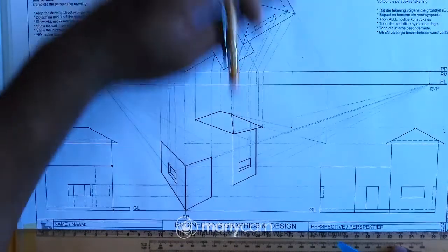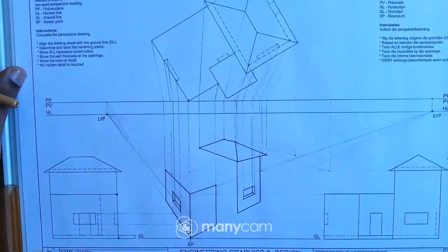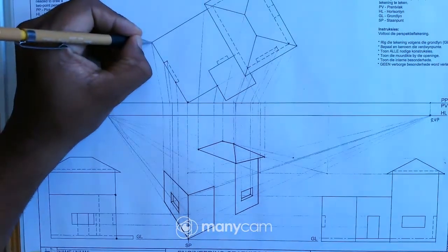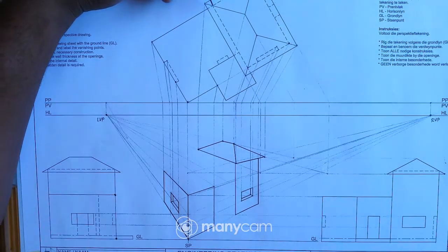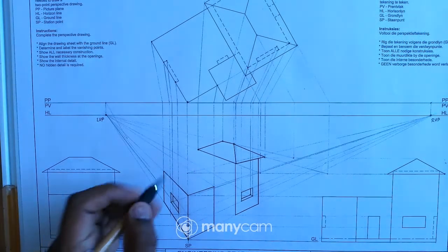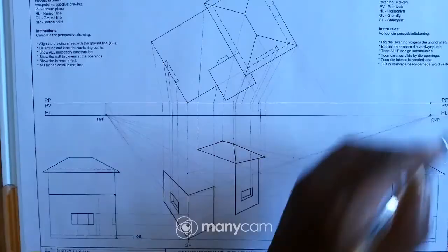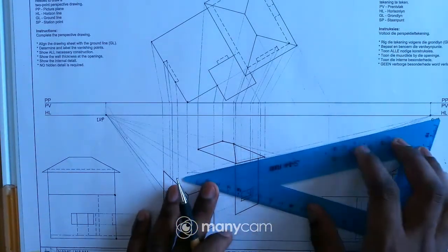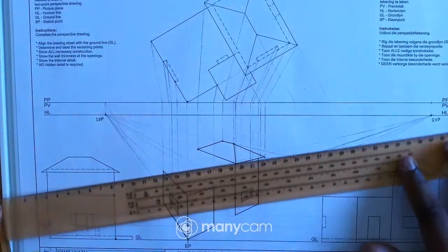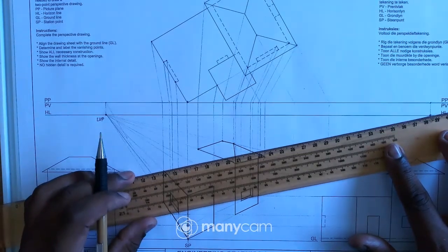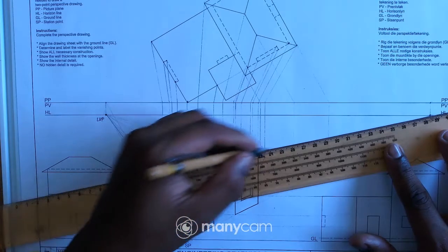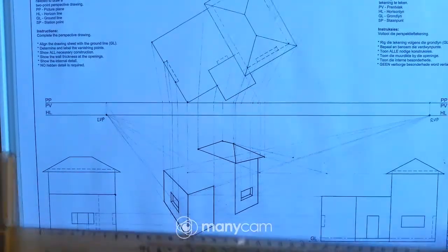That point from the top view is right over there, and you can see that there's a line going towards my right hand side, right? So I can just project this point to the right vanishing point. I can use my set square, my T-square there, to project the point to my vanishing point.